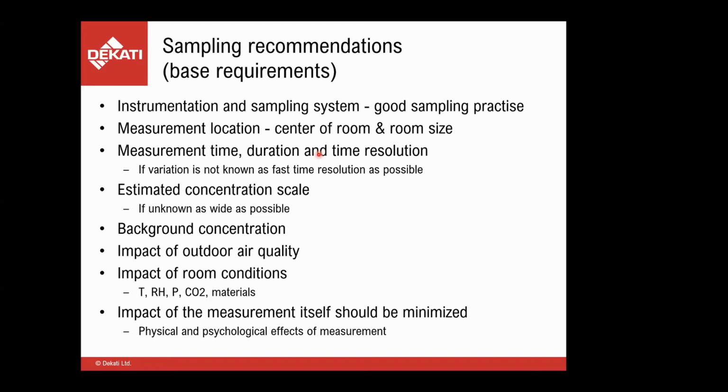and should be noted in the measurement notes. And of course, the impact of the measurement itself should be minimized. We already talked about the maximum amount of sample you are allowed to pull from a room, but there are also other things like, if the measurement instrument uses a pump, it's preferable that either the pump exhaust is very well filtered, or you use a dry or a scroll pump that doesn't generate aerosol itself.